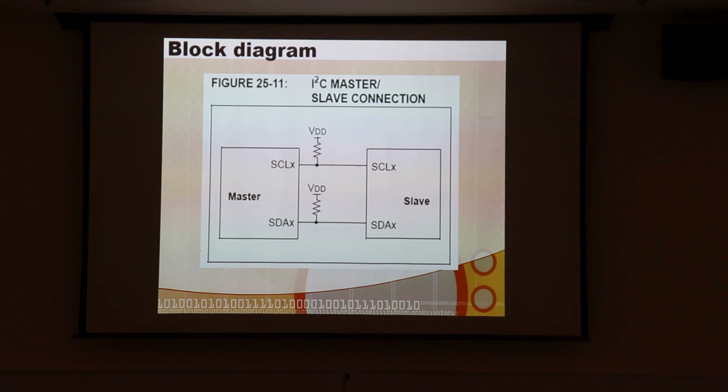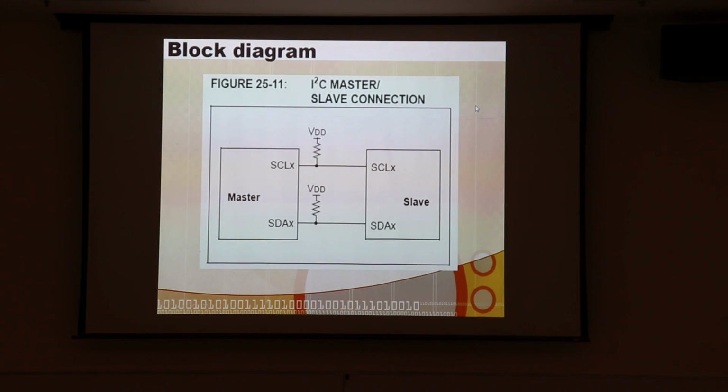It's really interesting. And so some of these little chips are quite smart, and they actually have some extra I2C going on. The real-time clock chips usually have 2 little packages on that, and you connect it to it with I2C. One package is the real-time clock.